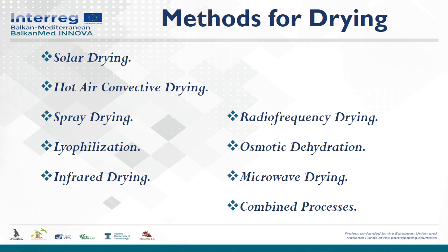The quality of spray-dried microcapsules is quite dependent on processing parameters of the spray dryer and properties of composition of the feed solution. The atomizer is essential because it determines the size of the droplets and conditions the efficiency of the process. Spray drying has proven to be an effective technology in protecting bioactive compounds and probiotics.